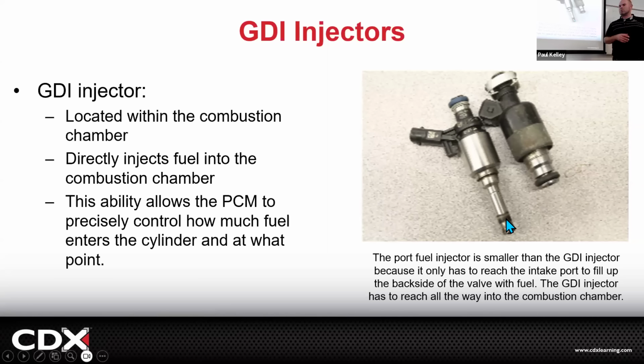This Teflon seal is a one-time use. These Teflon seals can be sizable, so it's not something you could replace real easy. A lot of times they have an expanding tool to get the Teflon ring in, and once you bolt the injector in, that's it. It's a one-time use. And if you're like, oh, whoops, I forgot, let me pull it back out? Yep, go get another Teflon seal and size it and get it all set up.